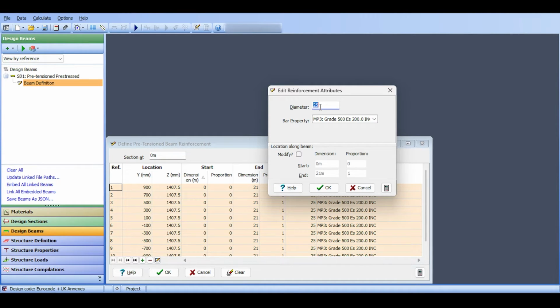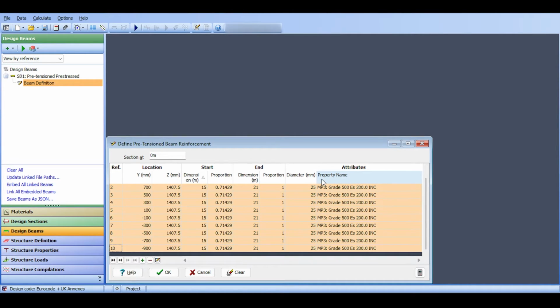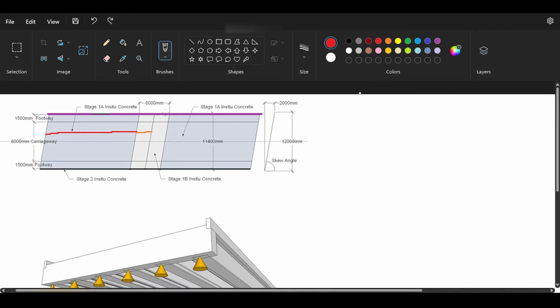I'm going to add the bar's location to be starting from 15. Why did I add it, and why do I want it to start at 15? It's kind of strange. Well, it's not really strange, because the entire bars are going to be connection bars between this and this. So that's why I wanted to add it 15. Kind of 3 meters on this side and 3 meters on this side. You could have the reinforcement fully on the entire bridge.